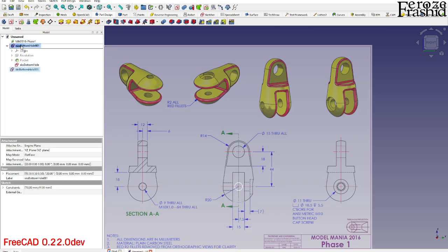So I have the same sketch twice. What I plan to do is I will take one on the left and one on the right. So this one, the one that I just copied over, I'm going to say this is for the hole, and I'm going to say thread. So this is one with the thread, and this is one with this counterbore. So C bore. Okay.